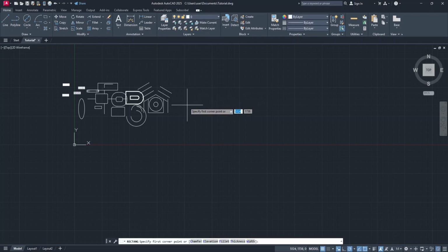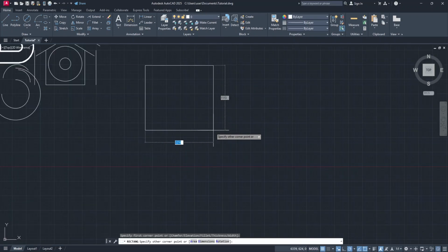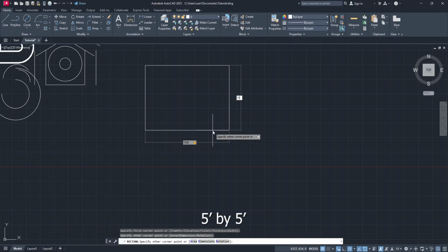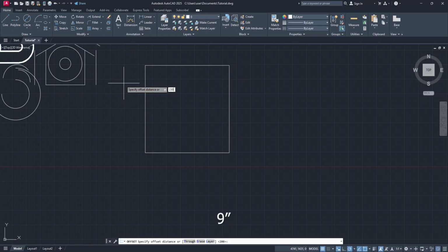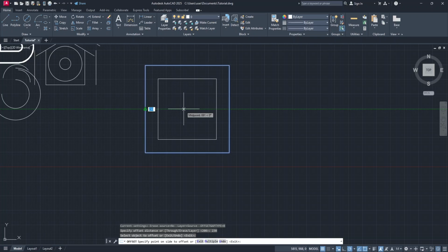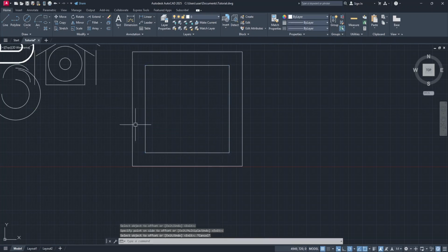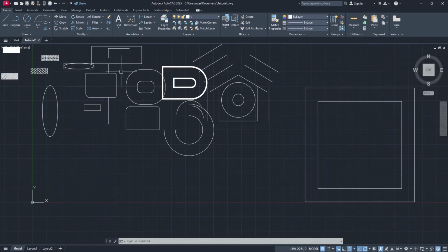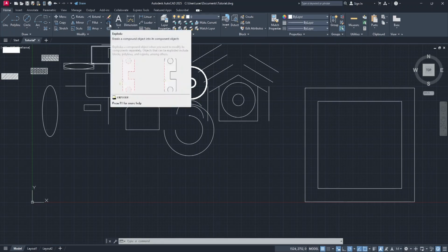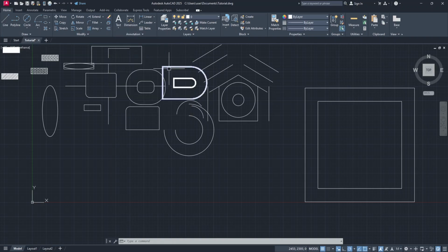Select rectangle. Click once. And let's make something like a toilet of a size 1500. Press the tab key. 1500. Press enter. Select offset. Give an offset of the wall 230. Press enter. Select this line for an outward and click. Press the escape key. Now, initially we've drawn a rectangle here, which is a polyline. There is this tool explode, which explodes a polyline back to simple lines.